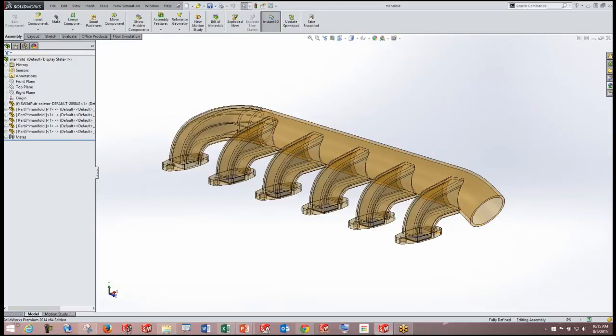And so my goal is to understand, if I have 1 inlet and I want to evenly distribute what's coming into these 6 different outlets, how evenly is that being distributed with the design that I have currently? Now, the knowns before I set up this study are that I'm going to have a static ambient pressure on each one of these outlets, and I'm going to have a volume flow rate of about 0.05 cubic meters per second into this inlet. And that's all I really know, other than that the fluid is air.